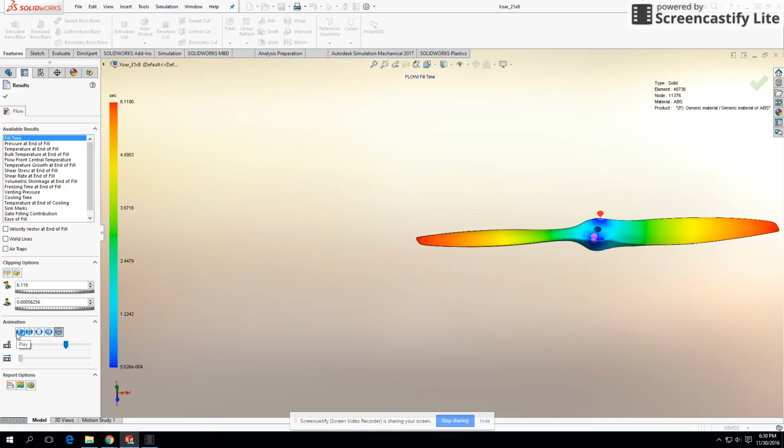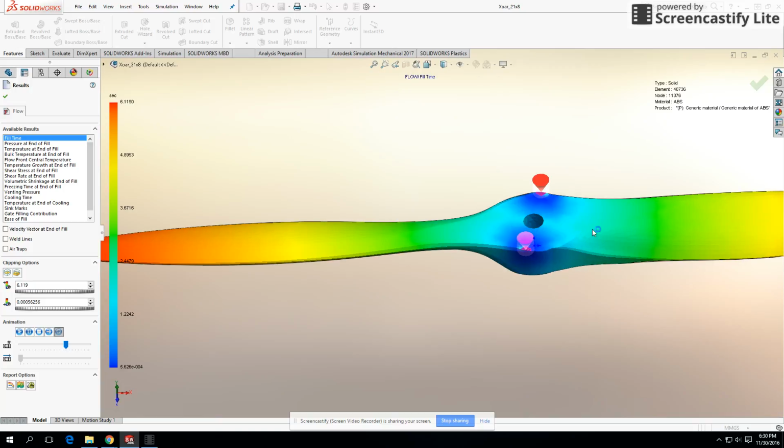Using the plastics add-in in SolidWorks allows us to simulate 3D model parts as if they were injection molded, and also not only quantify but qualify that part under our specific injection locations and vents, whether or not this is going to be a successful process. And then from the information we receive, how are we going to adjust the geometry of that part, considering thickness, but also material, and our method for molding and injection to get the best part.